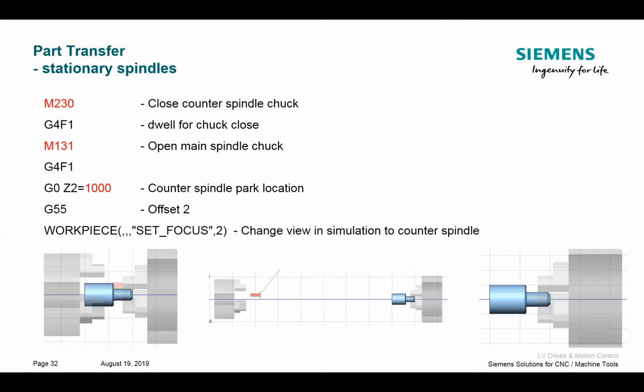So this way, all the other offsets are going to be taken into account. So, if you get an operator who says, oh, I don't want to send the subspindle back quite that far, I want it closer, I'm just going to edit this number. Well, that's going to mess everything up, because next you also have to combine that in the work coordinate for that position. Once we're there, load up G55.